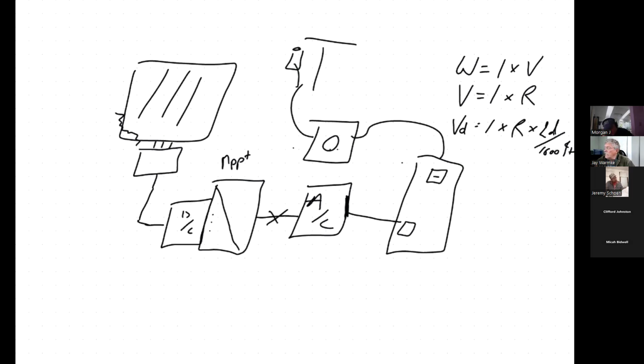So let's say in this example that I've decided to use 10 gauge wire, and this here is 280 feet from the combiner box to the DC disconnect. So it's a long way off. And I'm using 10 gauge wire. So I want to know how much voltage am I losing from here to here? So my equation says voltage drop equals amps. Well, what are the amps? In this case, I would look at the IMP on the solar panel because that's the actual amps.